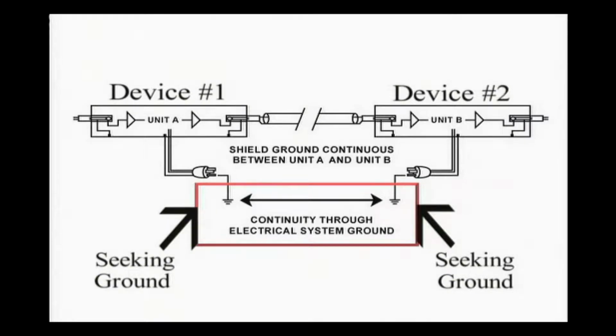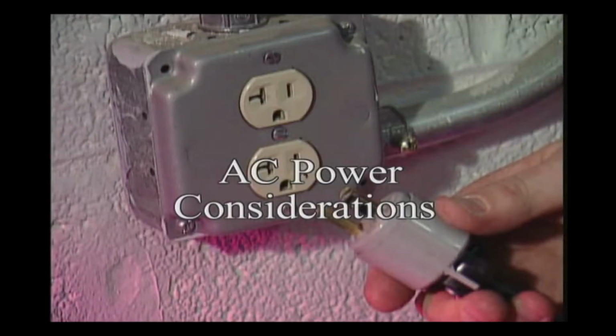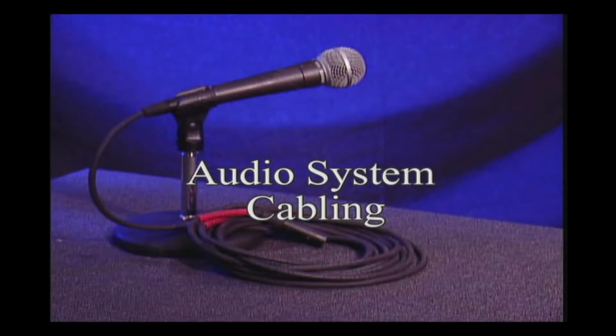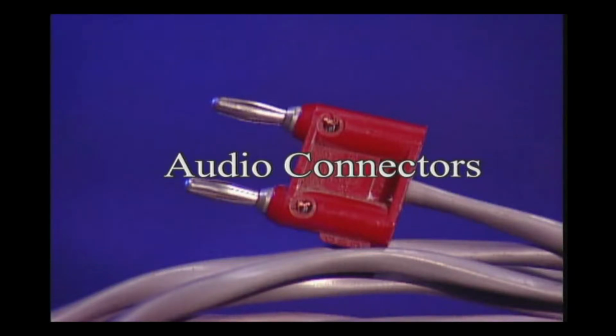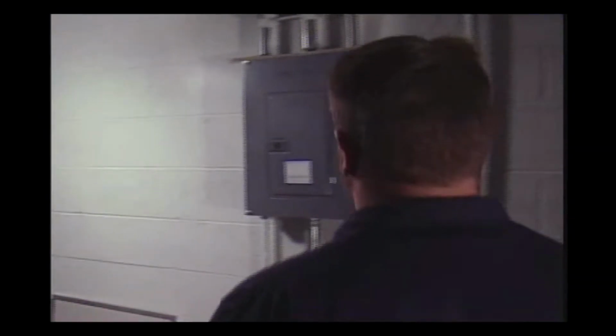To reduce system noise, there are 4 areas we need to focus on: AC power outlet considerations, using the correct audio system cabling, understanding how and where to interrupt the shield ground, and understanding the various connectors used within an audio system.